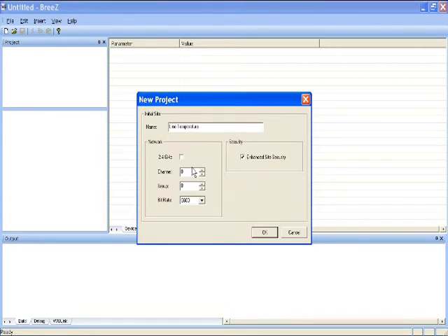The 2.4 GHz checkbox is for overseas hardware only. The channel availability is up to 9. The group availability is up to 999. You can set this as you wish, but please dial away from each other if sites are closer than 2,500 feet. The bitrate defaults to 9600, but is selectable to 115,200 if needed. The Enhanced Site Security checkbox should remain checked, and this will preserve the integrity of your data and not allow sites to crosstalk. Then click OK.